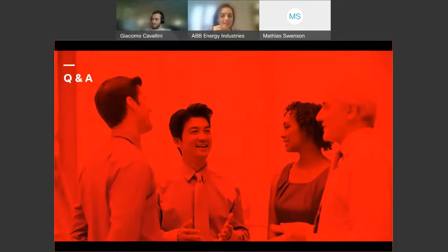Thank you, Giacomo. Second question is, do the compliance testing requirements happen on the actual system or on a test system? Here it's on the actual system. In most of the cases, let's take Australia now, for example, the tests are done at site during the first connection of the unit to the grid.